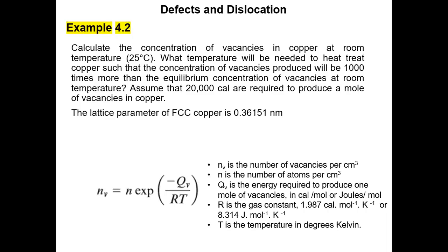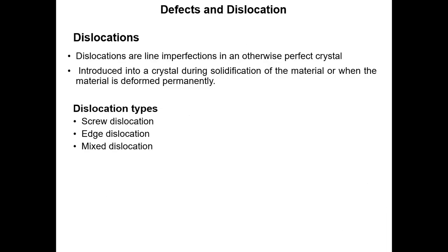Right? So this is all about the defects in crystal structures. Those defects that we first covered are called point defects. That means the possible defects at points. Dislocations are not point defects, we call them line defects or one-dimensional defects. That means a line of atoms is misaligned. We call it a dislocation. If we have a knee joint, it can dislocate. That means there are line imperfections.